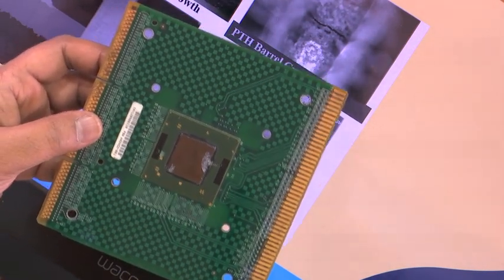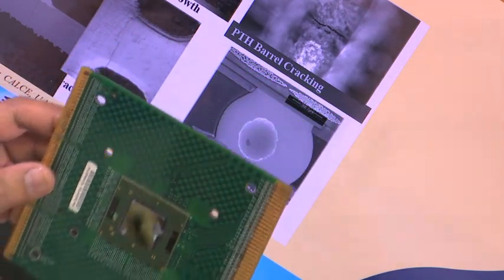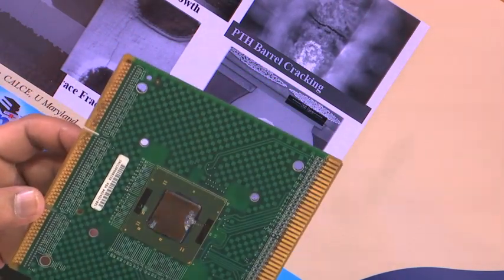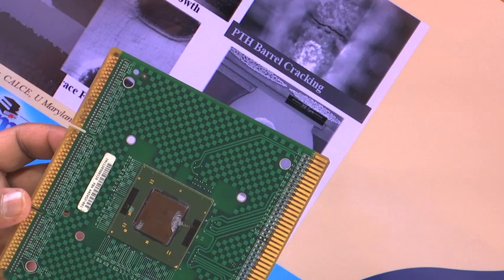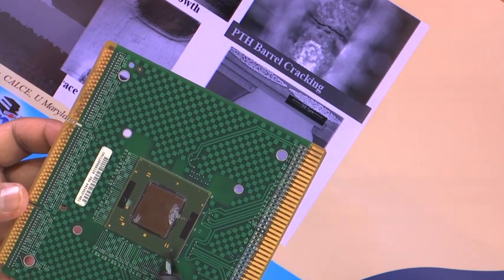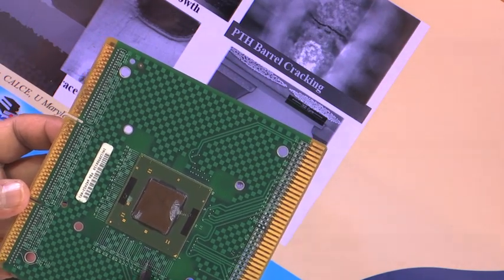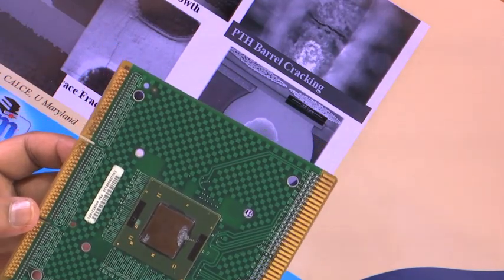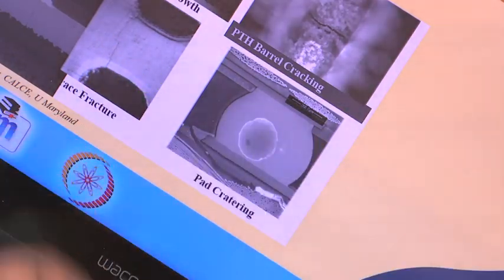Why? Because we go back to our first level packaging, we talked about underfill epoxy. Between silicon and FR4, because of the CTE mismatch, we use this underfill epoxy material, which results in reduction of the temperature induced stresses, clear. But why did we not have that between the package and motherboard? Because their CTEs are almost similar. So, why use it? Okay.